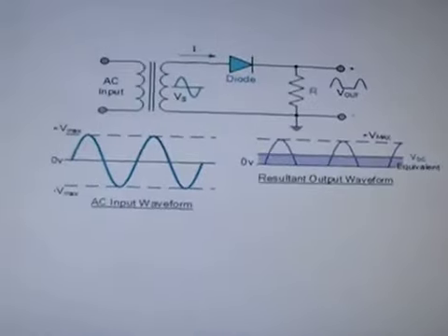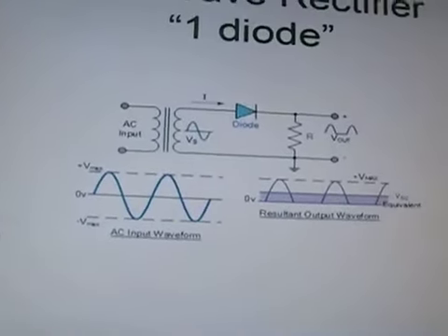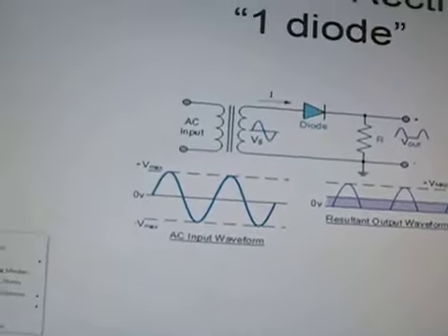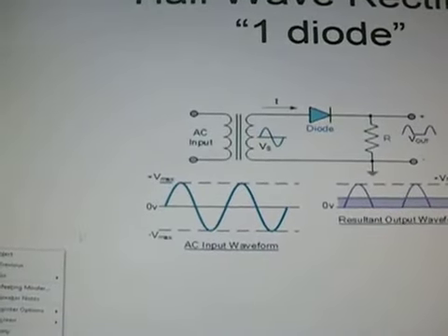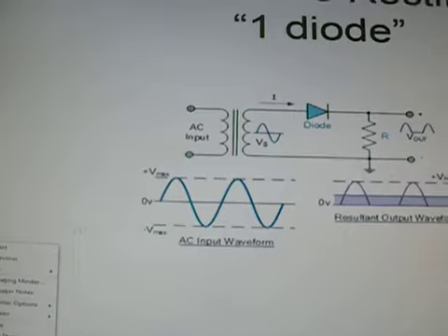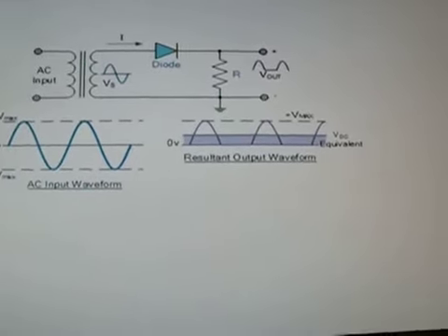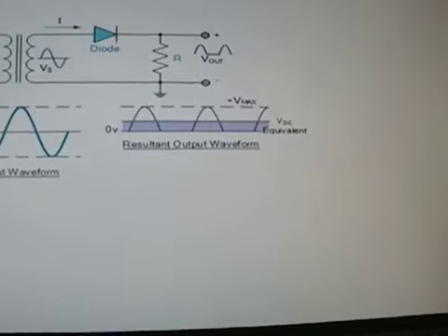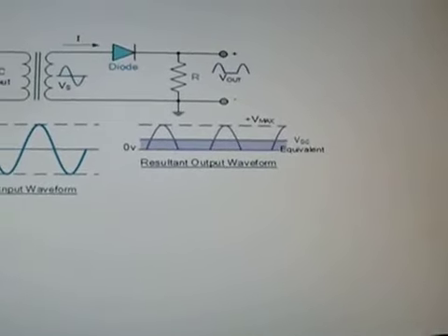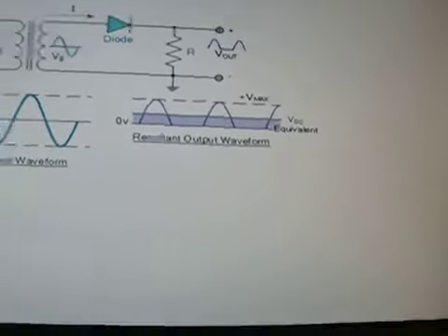Okay, here's another example of that. You have a couple different types of rectifiers that use diodes. Here's one using only one diode, a half-wave rectifier. You have AC voltage going in, and you get your pulsating DC out. But notice, unlike that previous picture, this one has a lot fewer pulses. Well, that's because it's only converting half of the AC signal to DC.